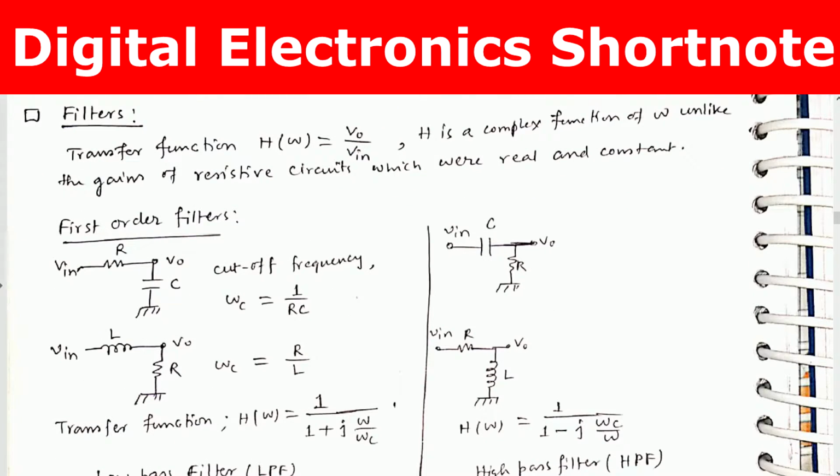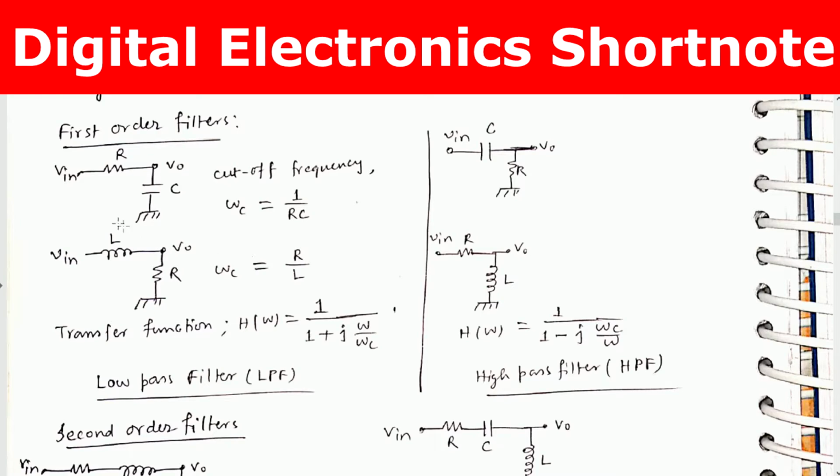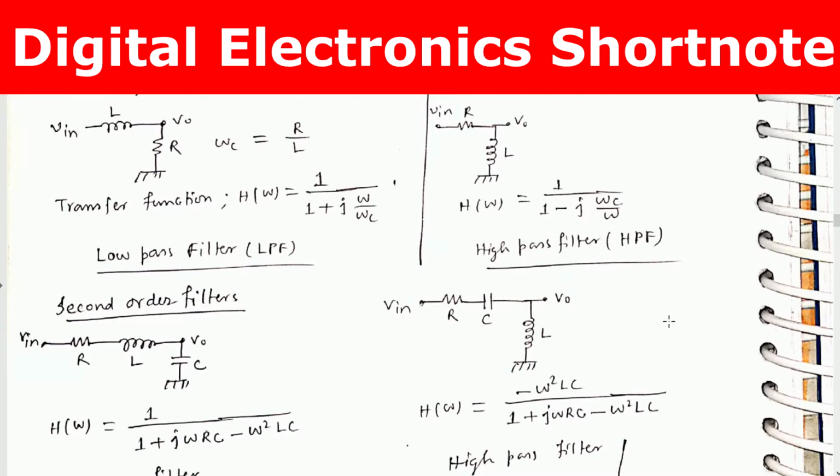Filters. Transfer function H of omega equals V0 by Vin. H is a complex function of omega, unlike the gains of resistive circuits which are real and constant. So these are first order filters using R and C, and the cutoff frequency omega C is equal to 1 by RC; for RL it is R by L. Transfer function H of omega equals 1 by 1 plus j into omega by omega C. Omega C is the cutoff frequency. This is low pass filter, and this is for high pass filter, just interchanging. The formula for transfer function H of omega is 1 by 1 minus j into omega C by omega.